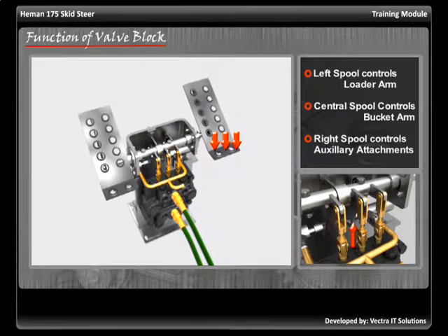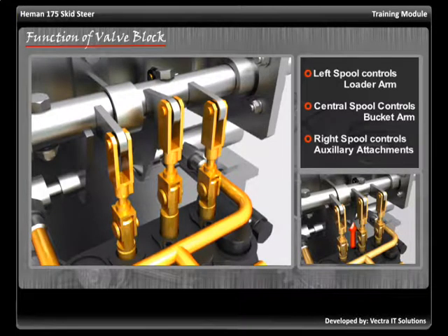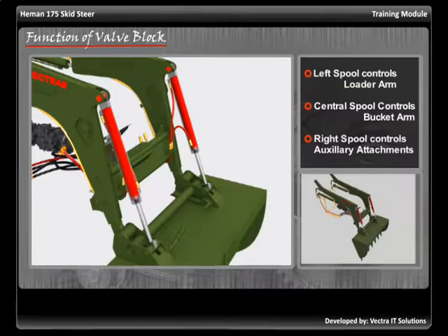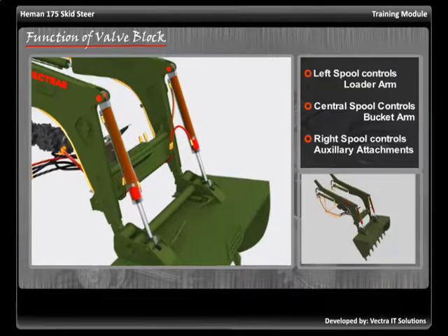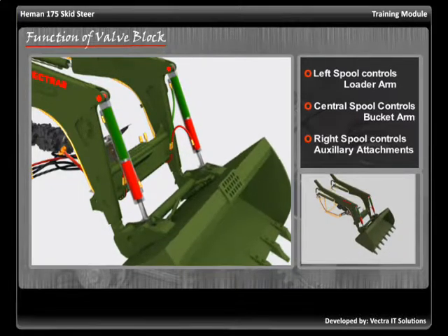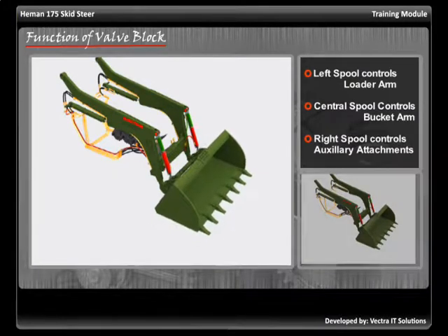Pushing the foot pedal by the ankle of the operator reverses the entire mechanism. The spool gets pulled up, and lower port becomes the escape route for the pressurized oil. The pistons of the cylinders are pulled in the opposite direction. This collapses back the extension rods of the cylinders, and brings the bucket back to its original position.